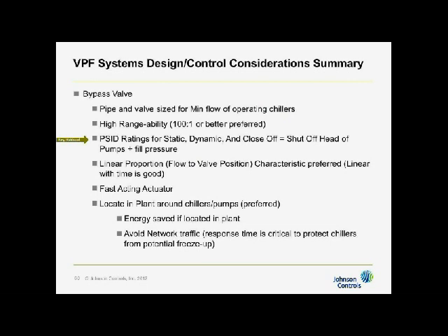The static rating is the casing of the valve. If you don't have enough pressure differential rating on that valve, you could burst it. The dynamic rating is the ability for the seat to remain in place and not blow out because the pressure differential is too great. And the close-off rating is the torque of the motor, the actuator on the valve. Has it got enough torque to close down under the pressure differential you could see at shutoff head? It's possible to see it in the system. And if it can't close, it'll sit there and chatter. Okay? So PSID ratings need to be up near shutoff head of the pump for static, dynamic, and close-off.